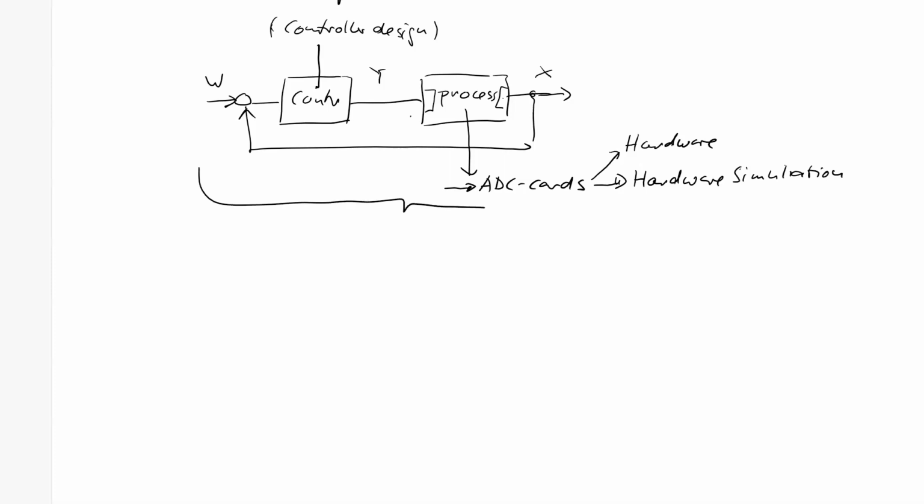Then the whole loop, including setting of desired value, including selection which type of controller you want to have, in defining how many steps you want to see for the reference step response, and with which sampling time you want to see this, there is the main point in menu real-time controller, the real-time functions, and the top menu point then has to be selected, which is called advanced controller.